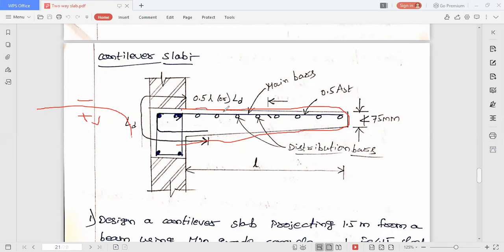and in between that there is a line, right? Here I have represented that with main bar. So that is main steel which resists bending. Okay, and instead of providing that bar at the top, if you provide it at the bottom, it will fail. Why? Because at the bottom compression is there, steel is not required. We need steel in the tension zone.